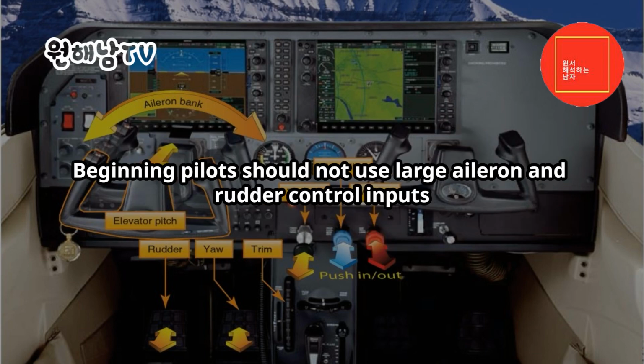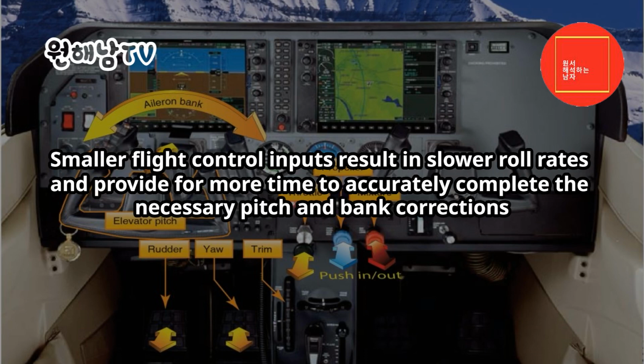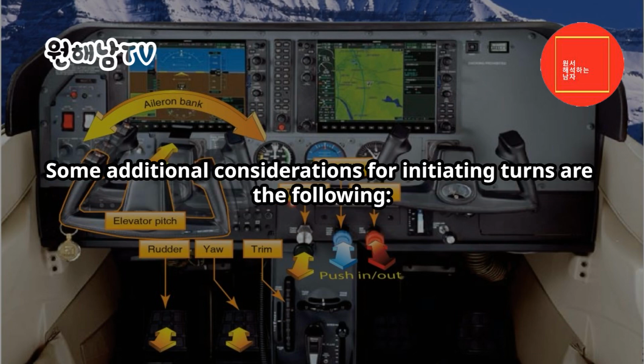Beginning pilots should not use large aileron and rudder control inputs. This is because large control inputs produce rapid roll rates, and allow little time for the pilot to evaluate and make corrections. Smaller flight control inputs result in slower roll rates and provide for more time to accurately complete the necessary pitch and bank corrections. Some additional considerations for initiating turns are the following.